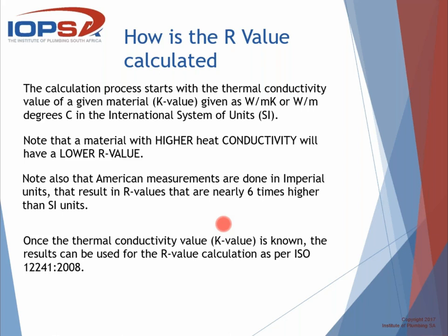And we know that we want R1, or this specified R1.5, or that specified R2. And so we have a simplified methodology of knowing what sort of insulation we need. So R value is a function between how well a material conducts heat through it and the thickness of that material. How much of that material do you need to achieve a certain amount of thermal resistance? And that's the value we're worried about.